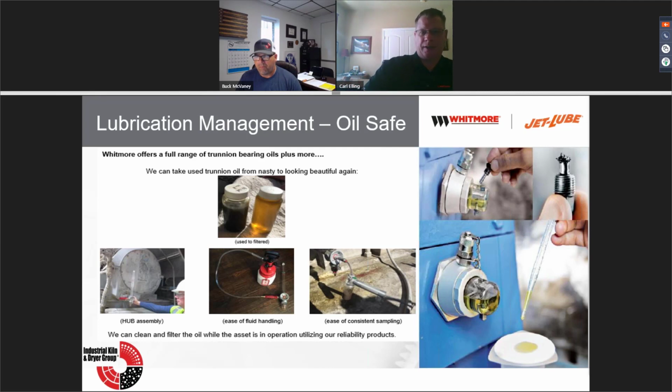Great tool, and it makes it easy, and you never open up the box. So you never open up the gear oil or the hydraulic reservoir. When you do open it up, you accidentally enhance the potential of adding more contaminants, which is something that you don't want to do. So this is really nice where it's a visual inspection, you walk by and keep moving.